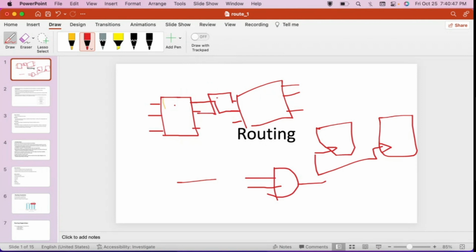Why do we concentrate on proper routing? After routing, your timing conditions have to be met. This is the main criterion for routing. Before routing, we saw CTS, meant for clock tree synthesis, where the clock is physically connected. Before CTS you have placement, and before placement you go for floorplan. In floorplanning, I mean chip planning, there is a term called power plan.